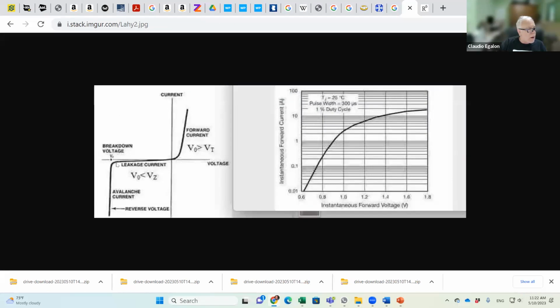Okay, so here you go. Here is the current versus voltage for a diode. If you have a negative voltage, the current remains very low on the negative side. But if the voltage is high enough on the negative side, then you have a breakdown of the diode. We didn't get in there. In our graph, we just worked in this region here. And we didn't get enough points here either. If you had gotten enough points there, we would be seeing this increase right here. But that's what you should get in your graph.